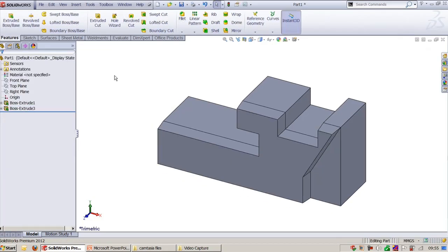This is how you can use close sketch to model when you create the feature. So this avoids the major task required to create the entire closed profile, and the software itself is giving you an intelligent tool to close the entire open loop.